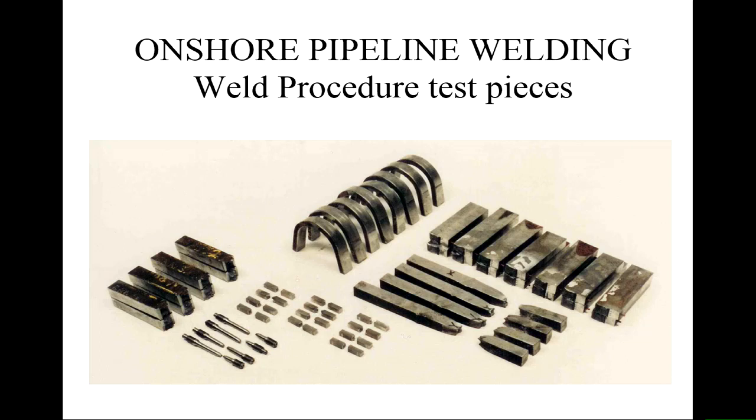So the welding engineer comes along and he sees a perfect weld with a good root pass, you can see from one side, and a good capping pass, good quality, workmanship standards very high, signs off the weld. But if he'd been sensible, he'd have thought, how could the welders possibly have done that weld in 2 hours, when if I calculate all the weld lengths and things like that, it's a 5-hour job? So he should have been suspicious.